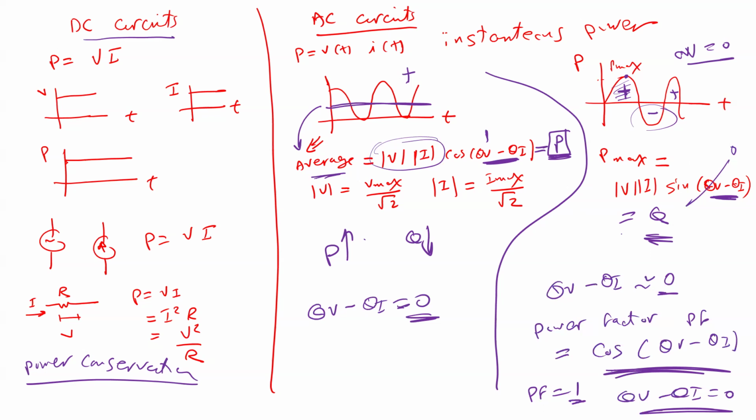For example, if the load is an inductor this way, maybe I will find that the power factor is very small, which is bad. So maybe I'm going to add an element so that when I calculate the total load, I find the power factor is close to 1. I will give you more details about this, but let me continue.